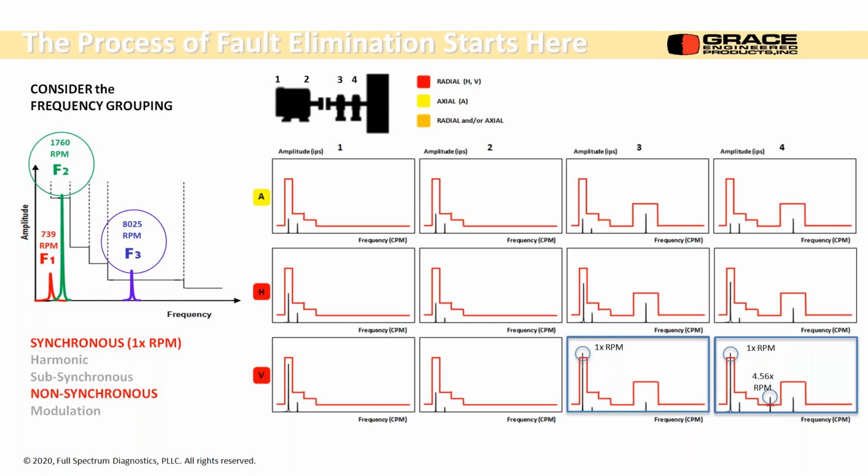So for the paperclip example, the number of cycles affects the failure. However, the example does not mention the time taken to complete each cycle, or is that not a factor? It is a factor in the metallurgy, where your cycles to failure type thing, but it really doesn't depend on how long it took.